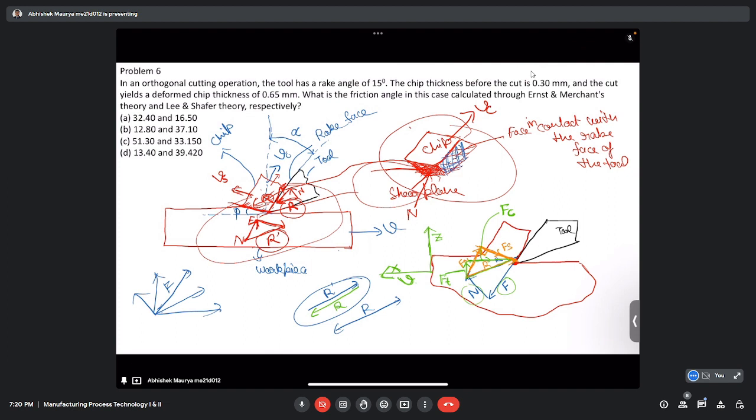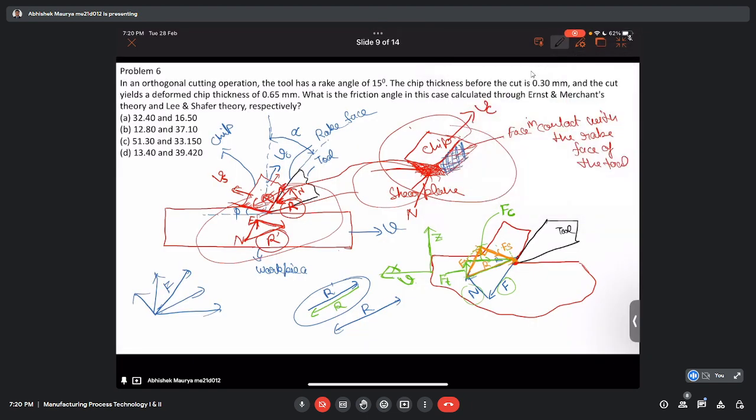And since they are components of the same resultant force, we can draw a circle with the diameter R, and that circle will definitely pass through all the other points. So I will draw the circle in black.